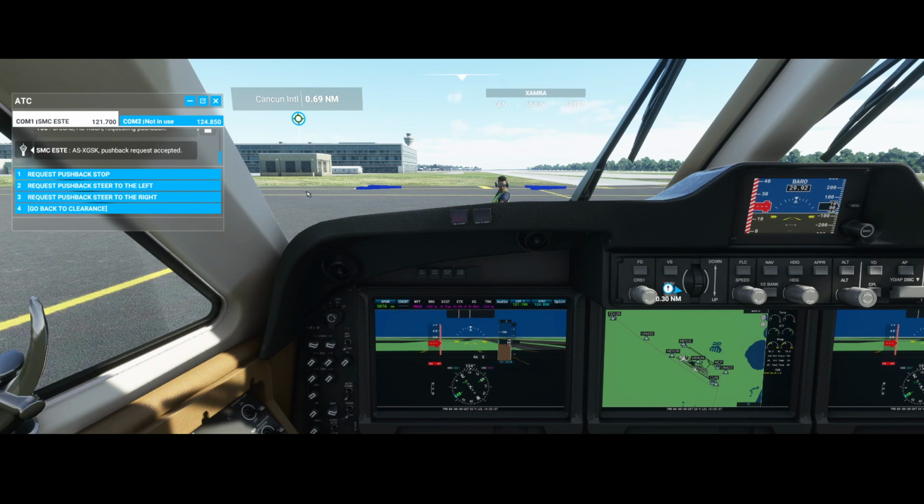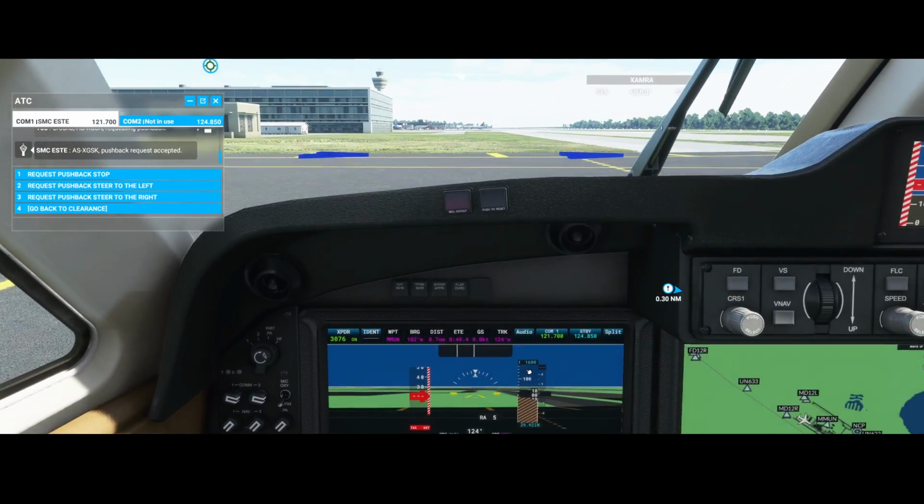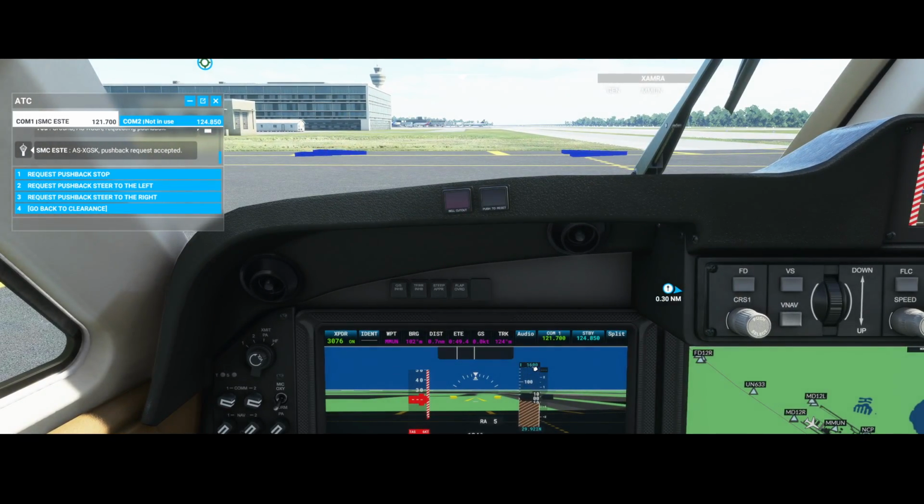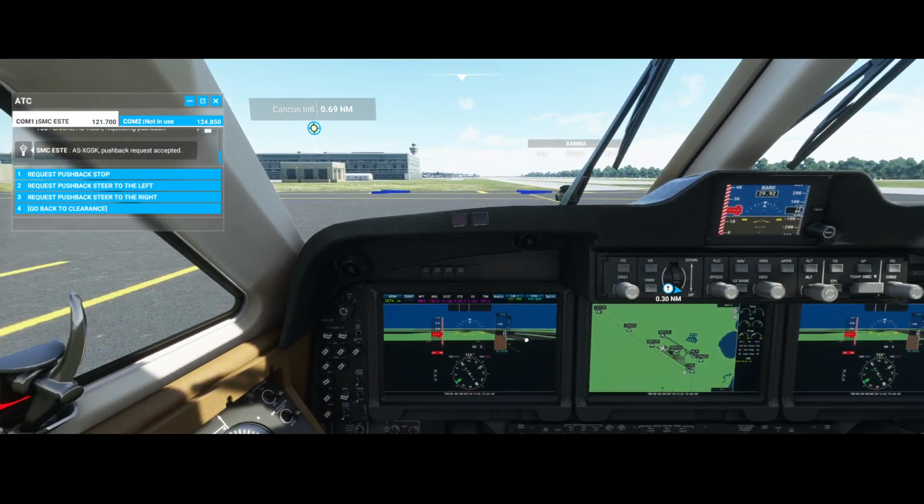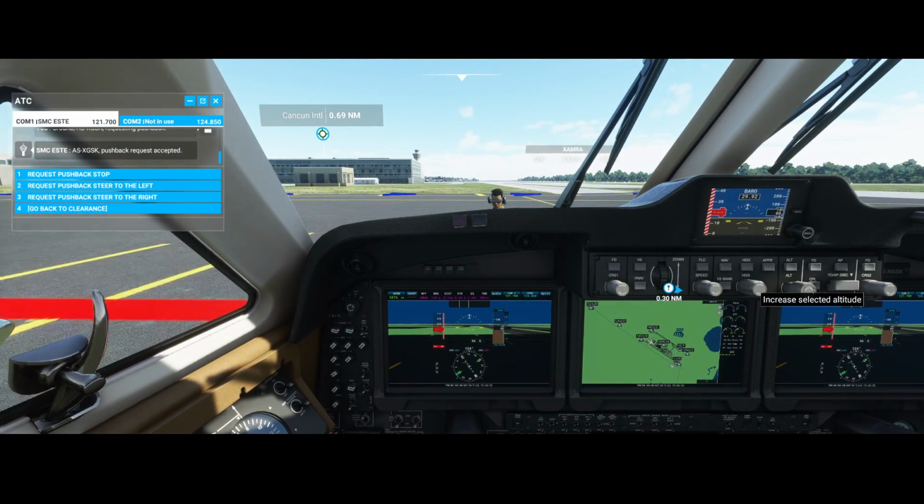And while we're doing that, we can configure the altitude which was instructed, right? So the altitude was 7,000 feet. That's something we can configure in our autopilot, and this is the first button we're going to discuss. If we turn this button, you will see that values will change. So let me do that. The values which are changing are the values here. You can see it's increased, currently at 1,600 feet. So I'm going to change it.